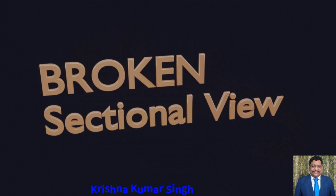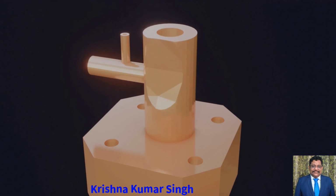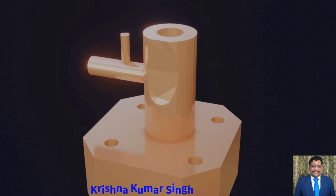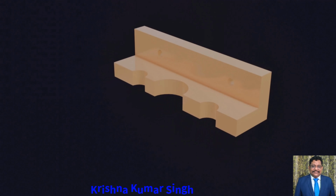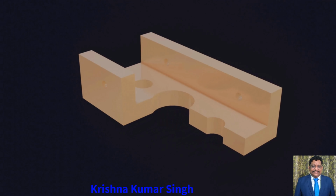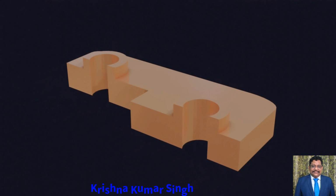Broken sectional view: when only a small part of an object needs viewing, then an irregular cutting plane passes through the object at the desired depth. The view of the left section of an object is a broken view. Different sectional views are clearly shown in this video with their respective cutting planes. So the obtained views give the desired configuration of an object.